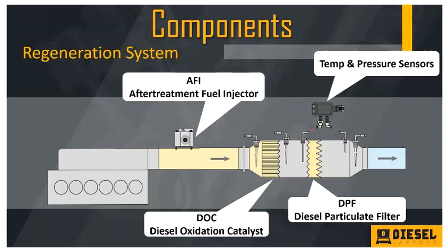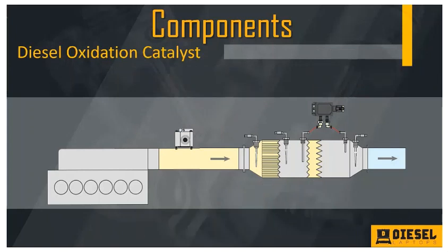But what you're truly measuring is flow. That's what helps us determine just how restricted our filter is. So we're going to use those values of that sensor during our diagnostics. We're going to look at our differential pressure sensor voltage, and figure out just how restricted we are.